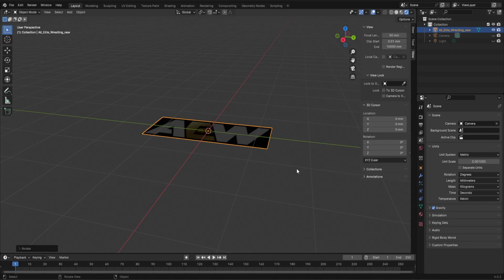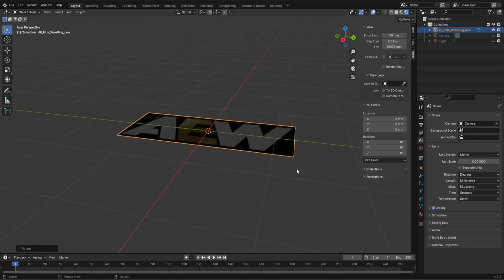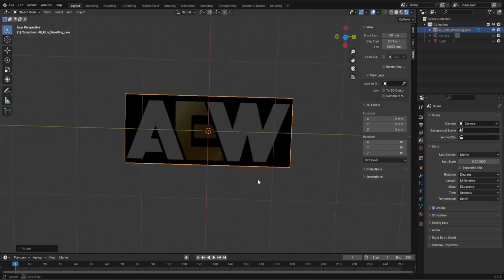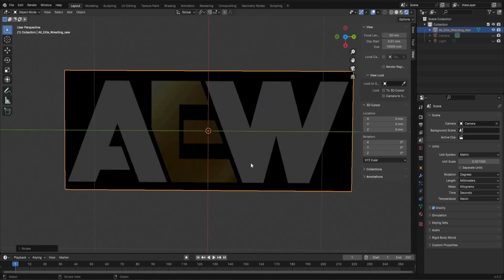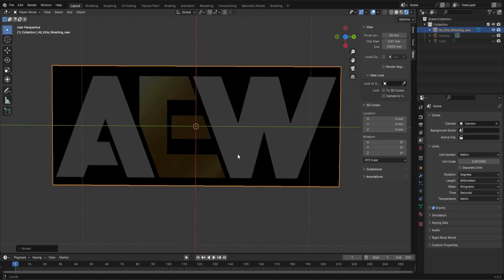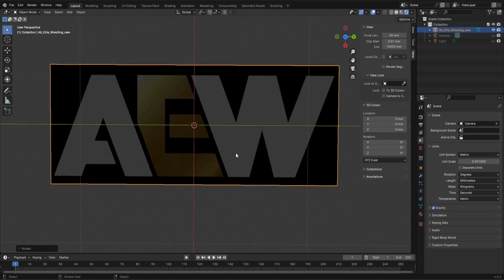To zoom into that object, I'm going to press the number pad delete key so I can see it like this. And then I'm going to use the mouse wheel to just rotate it towards the top so I have a nice view. I'm going to zoom in a little bit, and remember, if you need to move it to the left or the right, you can do that just by holding the shift key and then dragging it with the mouse wheel pushed down, and that will give you the ability to move it to the left or to the right.